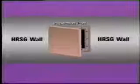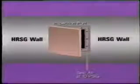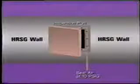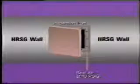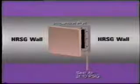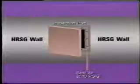Seal air fans provide a positive air pressure at around 10 psi or 0.7 bar. And this is arranged to provide a seal around the inspection doors. It is far better to have air leaking in than hot gas leaking out.